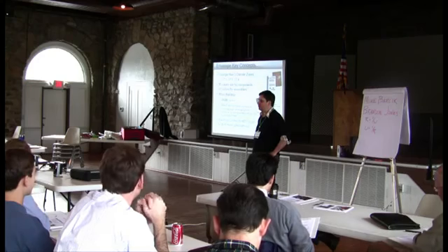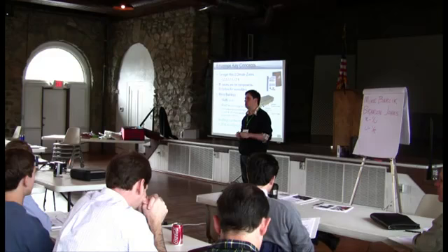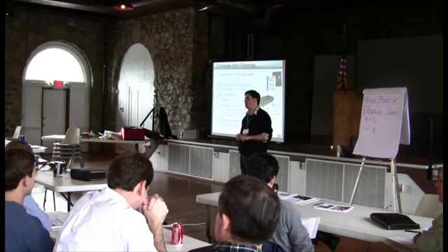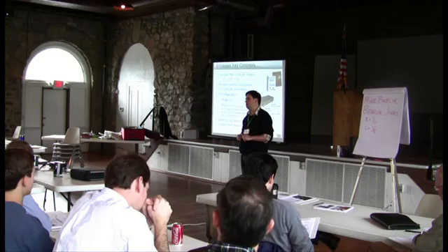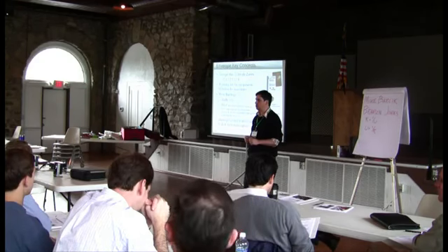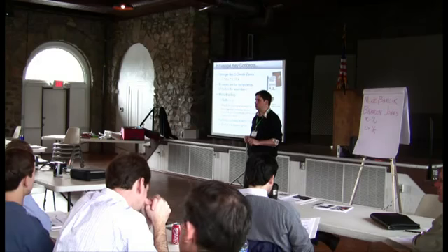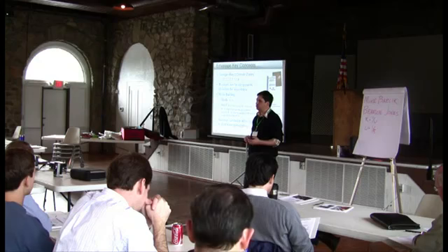So at the end of the day, though, I want to make sure you know what the code is, and if someone's going to use this commercial building as a commercial building, meaning they are going to condition it, it takes almost nothing in terms of supply air to basically kick you out of the semi-heated into the real conditioned space. If they put any kind of cooling or any kind of heating of significance in it, you're probably going to have to meet the code, in which case these rules do apply.